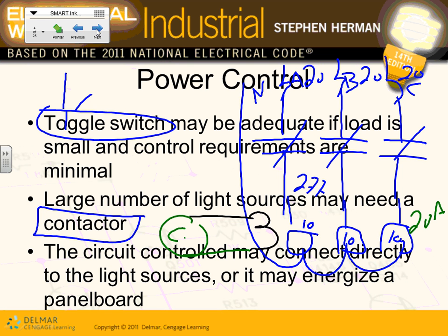The way we did our lights, guys, in the parking lot, I told you to put them on a timer. The timer literally will be a 20 amp timer. It's a contactor. What is the timer? It times out and opens contacts. So it's a cheaper way than putting in a big magnetic contactor like lighting contactors. Any comments, guys, about the lighting contactors versus switches?